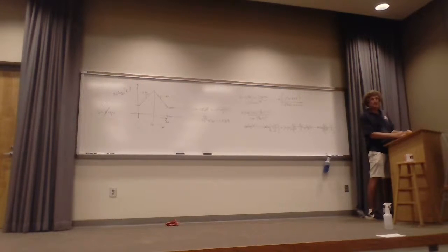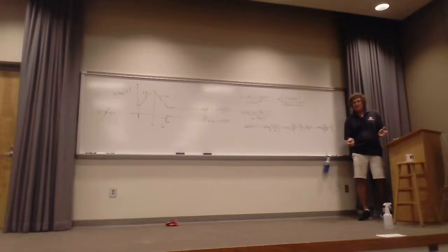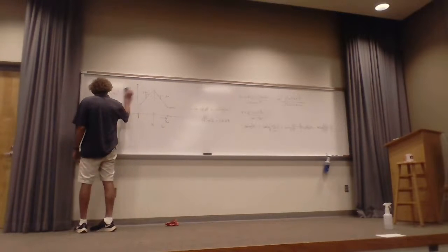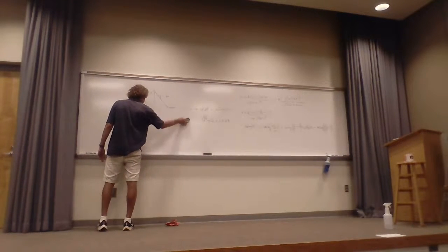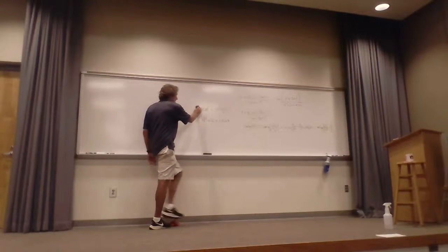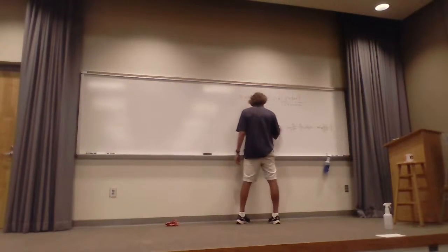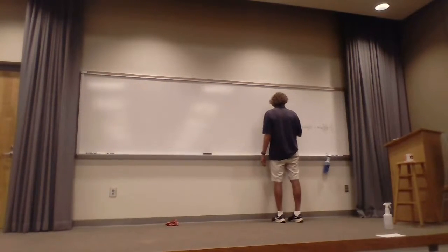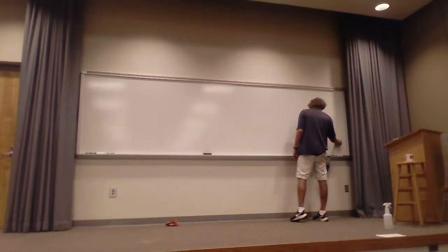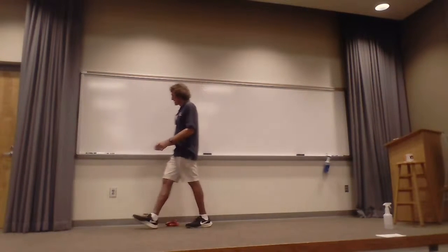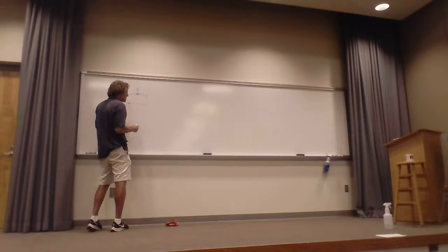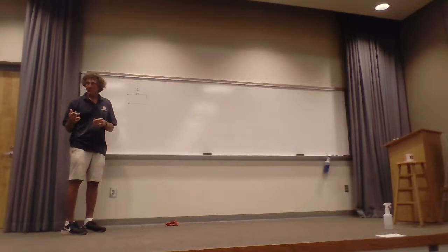If you didn't have any more questions about the homework, you can see, for resistors and stuff like this, here's something for a typical resistor. I want to just do this one. We could do inductors and we could do capacitors. But the Bode plot of a typical resistor is always nice to see, as well as a capacitor and inductor. But the resistor is the one, if you see this one, the others, you see no problem. For a standard Bode plot of the resistor, you have the resistor R here. We know the high frequency model of that has both capacitance and inductance, right?